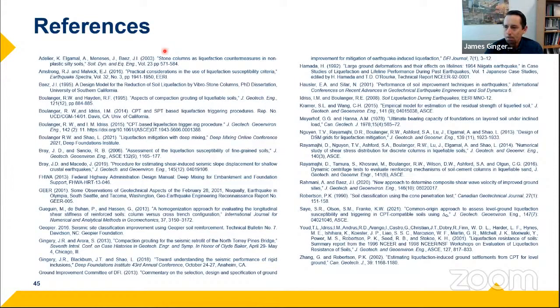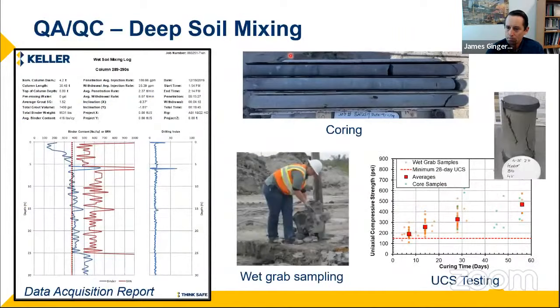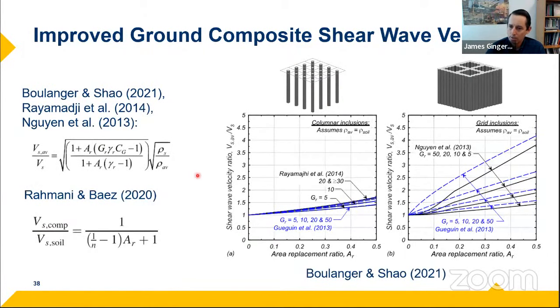On the other hand, if you like, and especially if you're counting on trying to change the site class based on the change in the shear wave velocity, you can account for that with these relationships to change the shear wave velocity, reevaluate VS30 or your site response analysis, and come up with changes in the spectral accelerations that you could use for design.